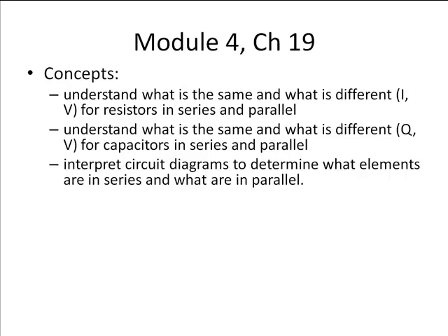If the things are in parallel, then you have to have just a wire connecting one end of the elements and just a wire connecting the other end of the elements. If there's anything else between, like a junction or another resistor or a battery or a capacitor, then they're not in parallel. You need to be able to write down Kirchhoff's current law and Kirchhoff's voltage law.